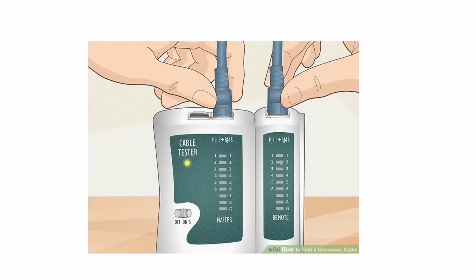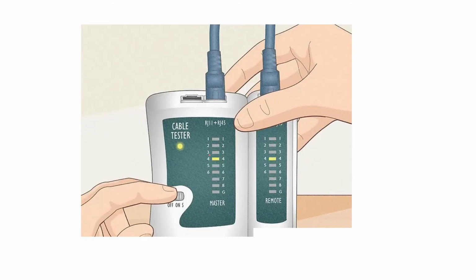Then this is how you are going to connect the cable with the cable tester, and you are going to turn it on with the on-off switch first. It will be running on a battery, and then this LED will go on. That is, you have made it on. Okay, and then once the testing starts, you can see pin number 4 here is glowing. That means it is connected properly. Pin number 4 is glowing. Like that, all the pins turn by turn, LEDs will glow.